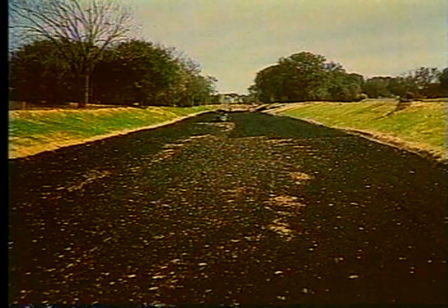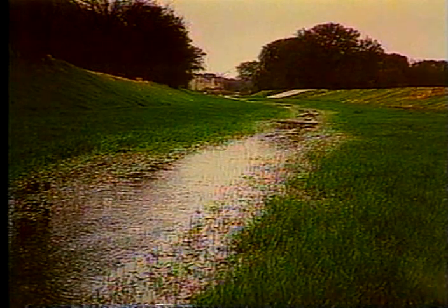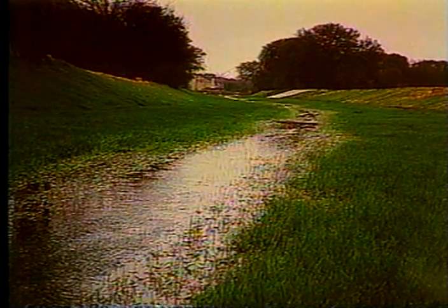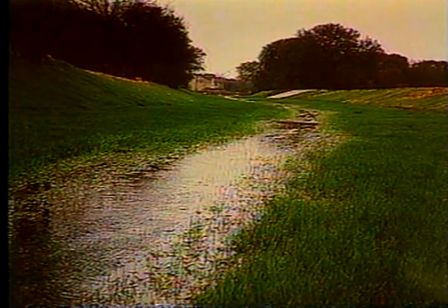However, where the flow of water is greater, down steep slopes or in perimeter channels, something more permanent is needed to prevent sediment from being carried away. Geosynthetic, non-biodegradable mats help to reduce water flow and protect the seeds. Roots become anchored in their three-dimensional matrix.